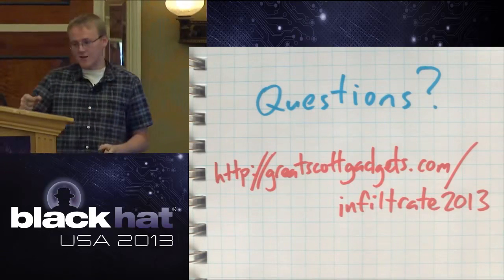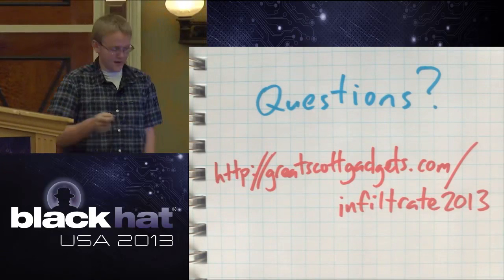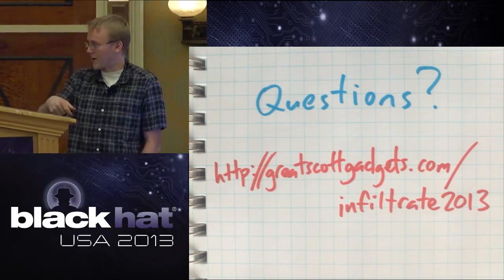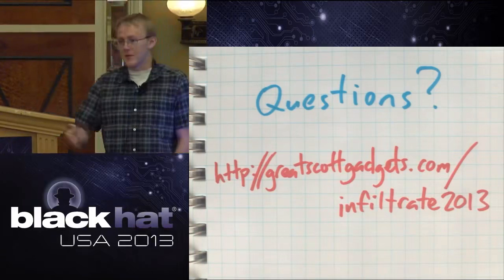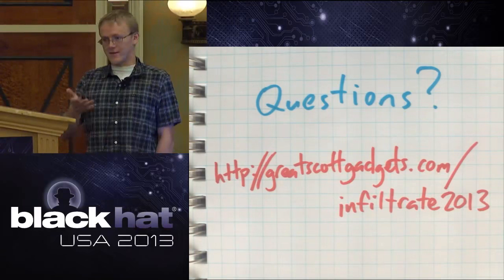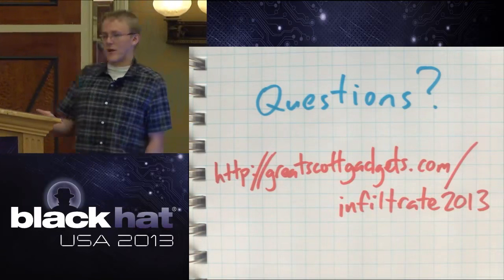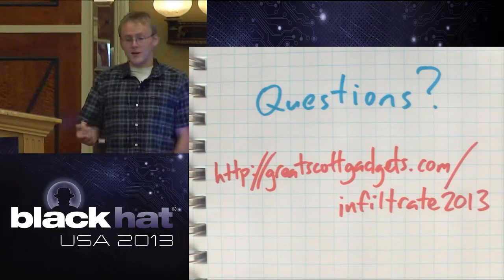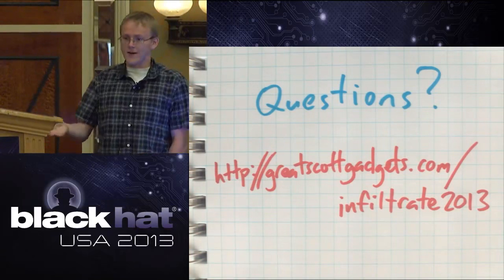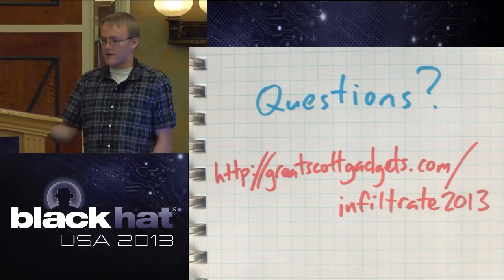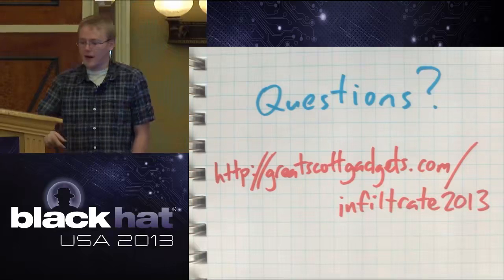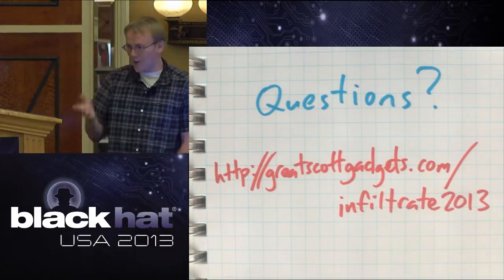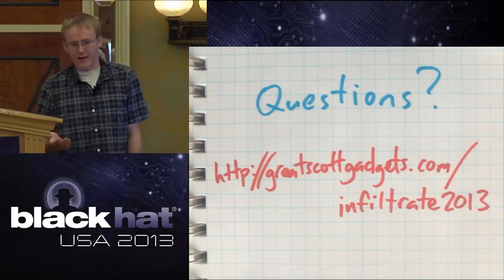You could take a specially designed audio jack and put it into the audio jack, and you can get serial data. In older phones, this has been around for a long time. In old phones, like the dumb phones, Nokia bricks or whatever, they had the same sort of deal because they didn't want to have pin outs or tons of extra components. They would just combine them together, and that's how you would program the phone.